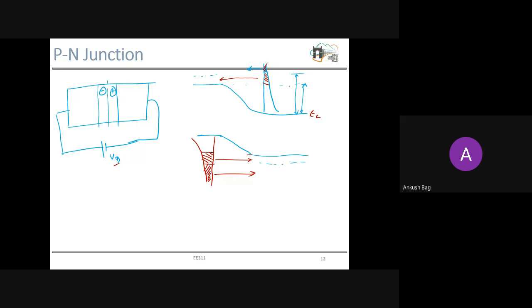See, this was before the forward biasing. So this was the potential barrier psi naught. Again, if we recall from our previous module, we calculated how many electrons or carriers will be there above energy q psi naught. This we have seen in the Fermi-Dirac distribution discussion. So the number of carriers will be proportional to e to the power minus q psi naught by kT.